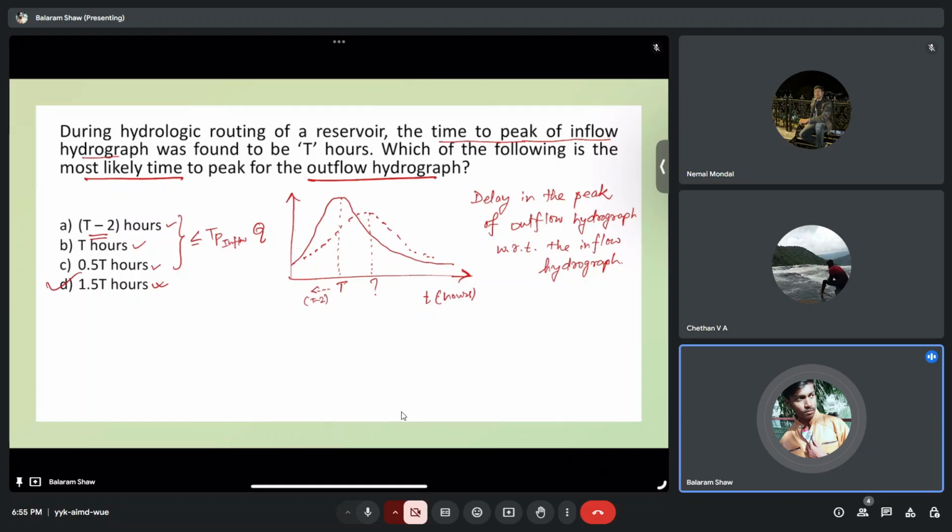So S1, and what all we need, we know the outflow also at that time, and what we do, we take all those things in the left hand side, that is S1 minus O1 into del T by 2, and the remaining unknown we will keep on the right hand side, that is S2 plus O2 into del T by 2. We just use the same equation, we just reshuffled it based on whatever is known to us.